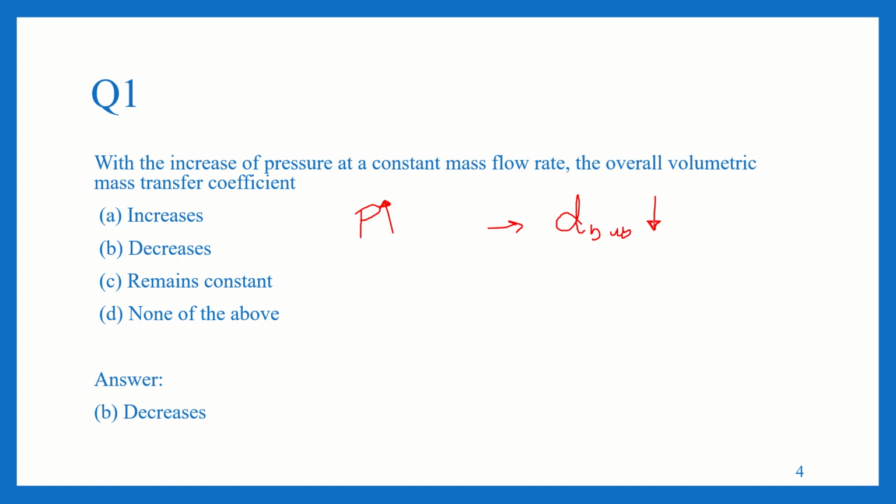So what happens when bubble size decreases? Not increased mass transfer rate, sorry. There would be many bubbles, like bubbles would be broken down. So there would be n number of bubbles because of the decrease in the bubble size, and this would lead to, here we have fluid, right? The bubble to fluid mass transfer coefficient would be decreased, like the mass transfer coefficient would be decreased when the bubble size decreases.